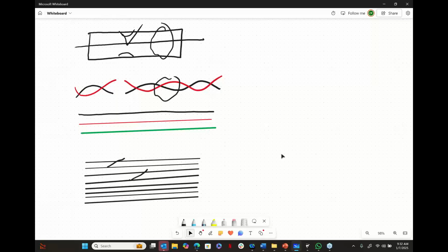So understanding, let me throw out another example here because this is key later on, since a TDR is looking for impedance mismatches. If you took a twisted pair cable, cut open the sheath and pulled the conductors apart like this, again, a signal is still going to pass through that just fine, but you have changed the relationship of the conductors. So a TDR also sees that as an impedance mismatch.